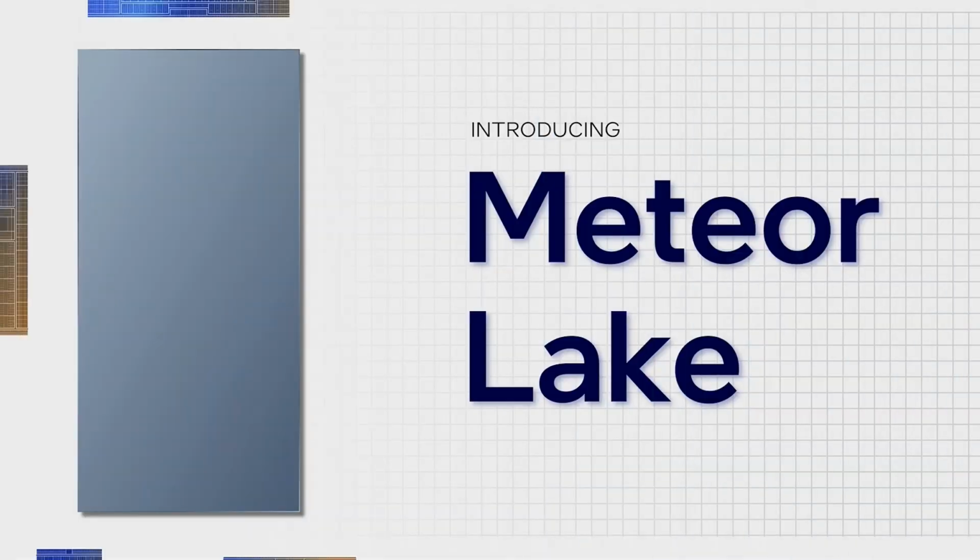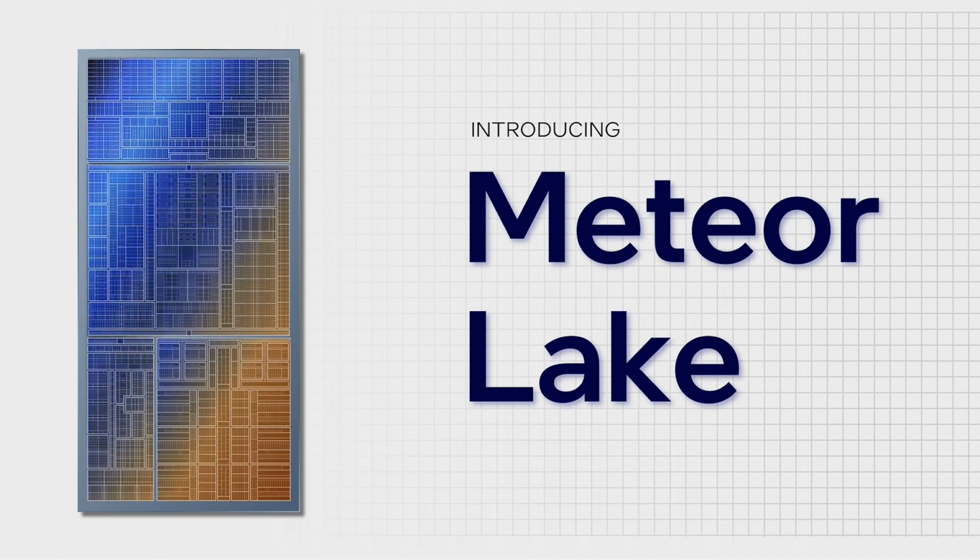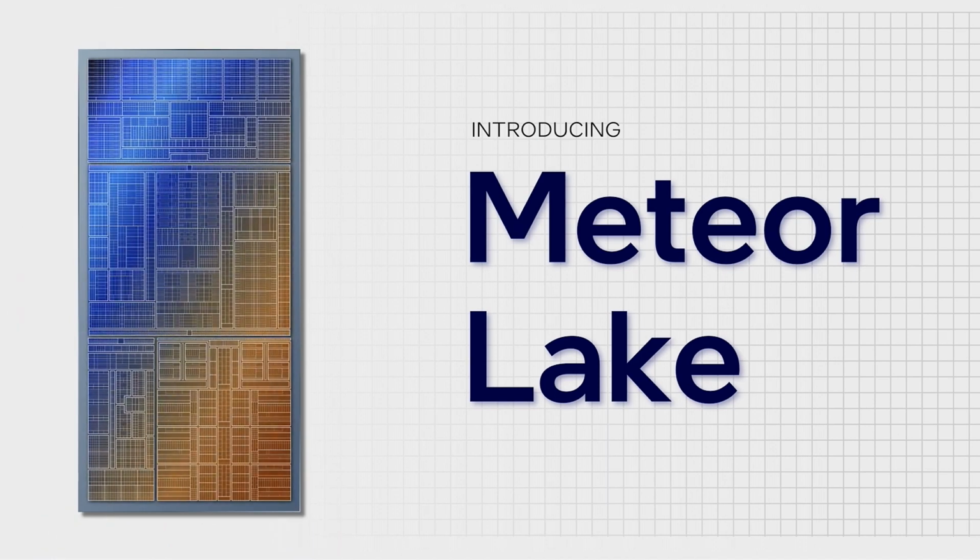Strategically, what we figured out is not all IPs in the entire Meteor Lake need to be on the latest cutting-edge process. There is an optimization that you could do across power, performance, cost vectors, and that gives us the ability to split the die into multiple tiles and tailor the IP for the process node that's best suited for it.